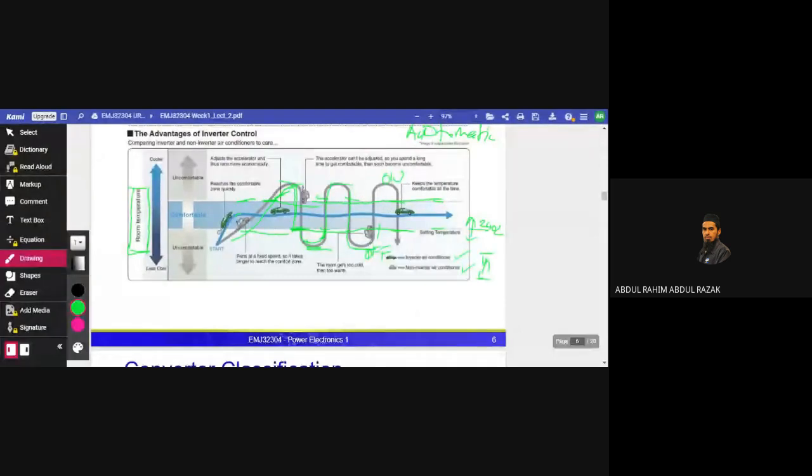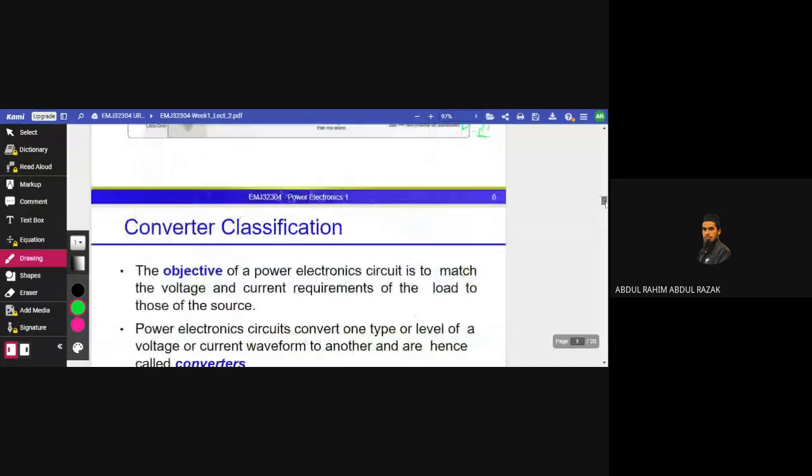Let's say we have an AC machine, so we can control it by changing the source frequency, because the AC machine will rotate based on the source frequency. If you supply 60 Hz or 50 Hz, the rotation will operate the same as the incoming voltage frequency. But how to change the frequency, that's where the VFD comes into the picture.